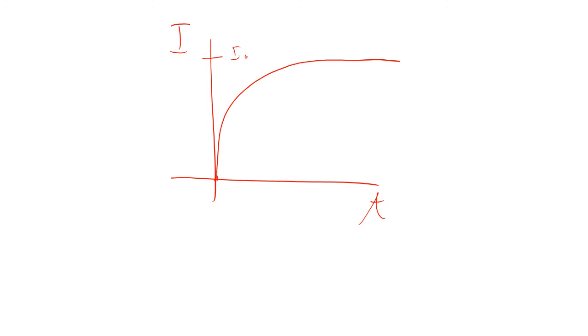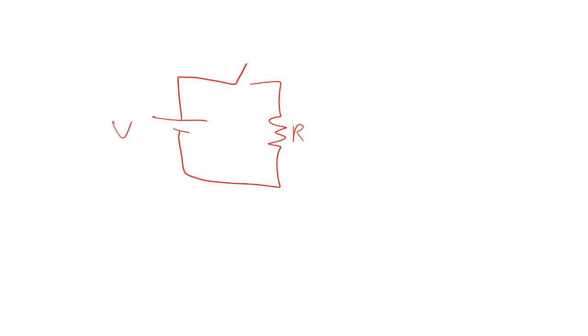And in fact, if you had any circuit whatsoever, even our simple circuit that we talked about a long time ago, in which we have a V and an R, you close the switch and current starts flowing. Because current starts flowing, you get a magnetic field in here. Because there's a magnetic field, you're changing the flux. The change in flux induces an EMF that way. Even this little tiny circuit would have a tiny bit of self-inductance.